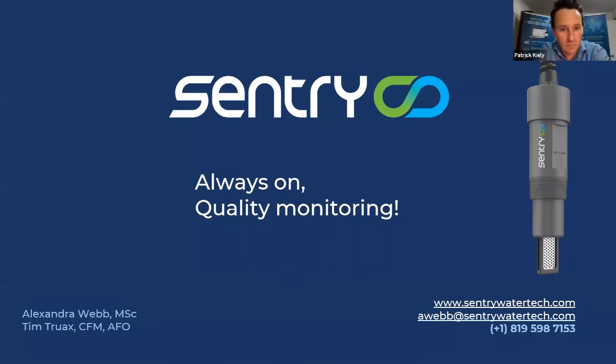Fantastic, thanks, Alex. So we have two questions, one from Adele. If it's a nitrification reactor, our biology that grows on these sensors is carbonaceous. So what we can do is put sensors before nitrification, in primary clarifiers or post-aeration basins, and still flag those biological upset events. We can flag those events in the wastewater to say, look, something is clearly inhibiting biological activity at this part of your process. Be aware, because it's going to also impact downstream processes. That's what we're very good at: when there is carbon in the wastewater, flagging those massive changes or significant events so that you can be aware of them for downstream.